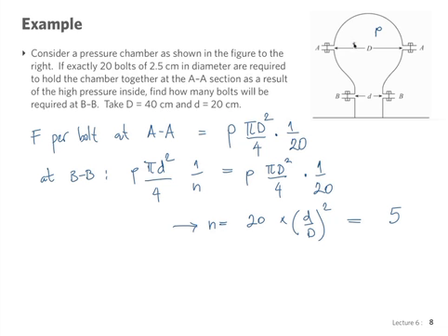So you know what we're using here? We're using the concept of shortcut number 3, basically, which is that in this curved surface we have pressure operating everywhere, right? Everywhere. But the total pressure force is actually on that projected surface. The total force in that direction is basically the same as the pressure on the cross section here, and the same for any curved surface.